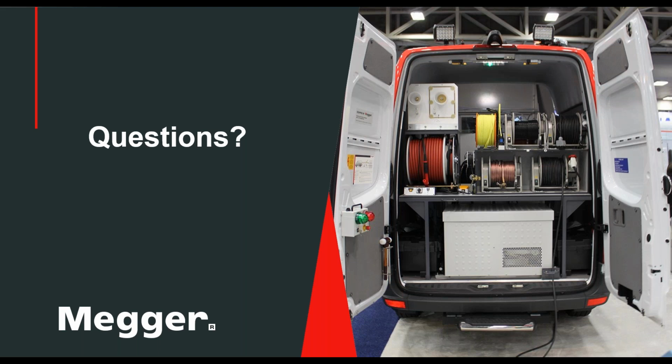So on those types of PILC cables, you are probably going to be using a bigger thumper. But the rule would stay the same. With that bigger thumper, you want to use the lowest voltage range that you can get away with, because that's going to give you the most joules at the lowest voltage level.